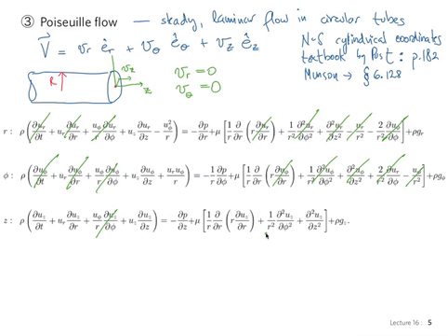So I'm just going to write the result. We have our dp/dr remains with only our gravitational term. Everything else is 0 from the first equation. And for the theta one it's the same thing. We only have the d theta with possibly the component of the gravitation in that direction. Everything else is 0. And then in the z direction we have only a component of the velocity z. So I'm going to now erase that, and I'm going to write these simplified equations. Okay.